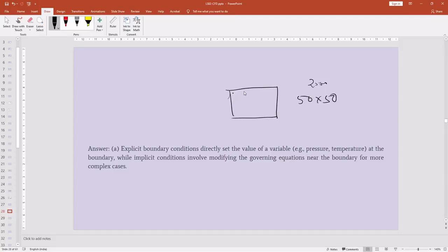You can use anything, because all this is an iterative solution. We will be using the Gauss-Seidel method, and TDMA, the tridiagonal matrix algorithm. You can use C, C++, MATLAB, Python, anything comfortable that you can learn. Because if you don't know coding, you won't know how we are calculating, since the meshing and solving of the algebraic equation are done separately.